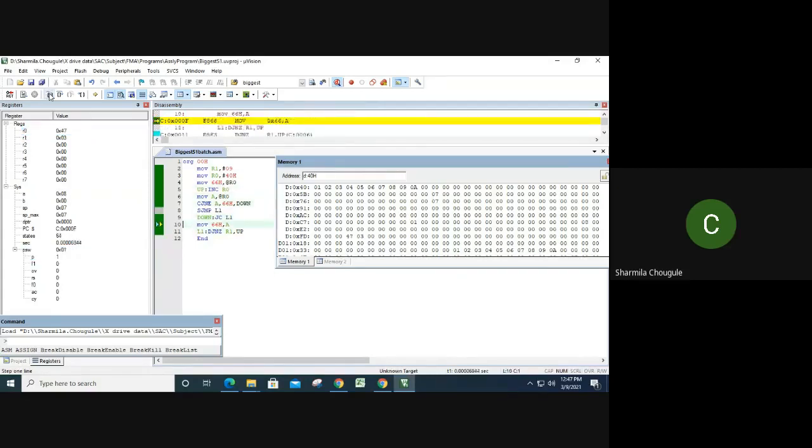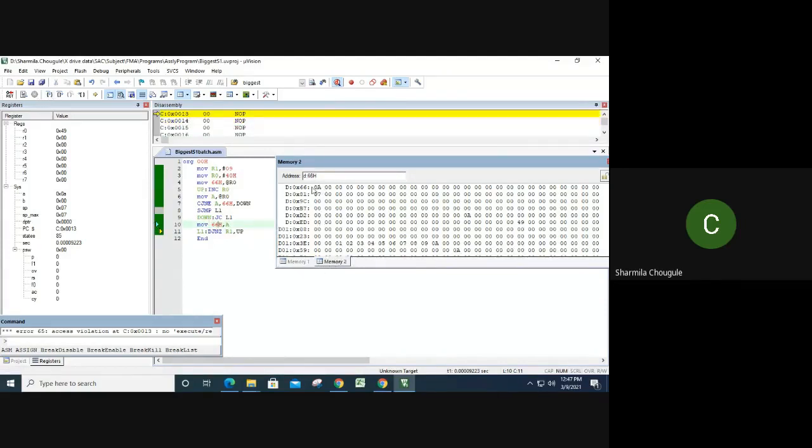So it has become 3, 1. This is the last loop now. The counter has become 0. Now you can check your answer, which will be stored in 66H. Your answer has been stored in the memory location 66H. From the 10 numbers from 0 to 0A, which is the largest number? 0A, and that has been stored in the memory location 66H.